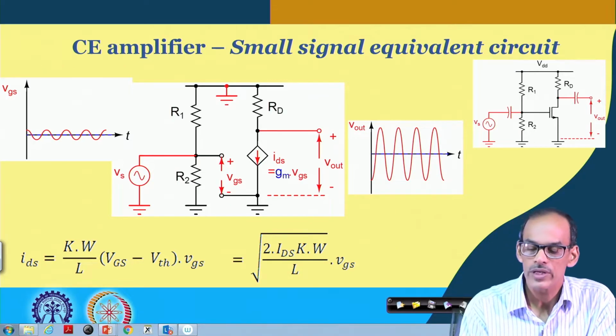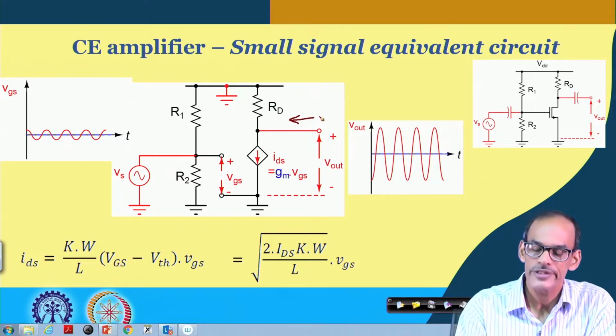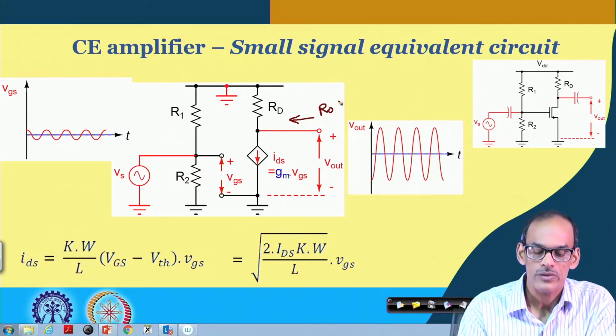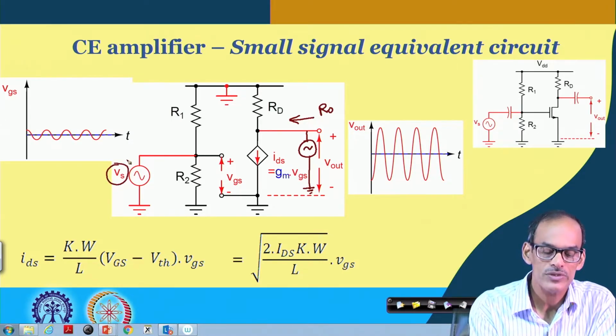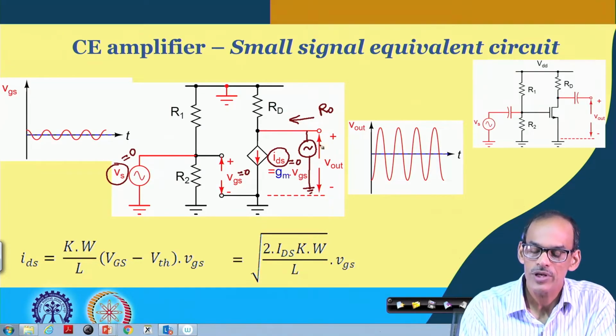So, if you look into this circuit from outside, and see what is the corresponding output resistance. While we will be doing this, as we said, we can connect a signal source here, and then we have to make this part equal to 0. So, once you make this equal to 0, this part it is 0. So, that makes this current also 0. And then if you stimulate this output port by say Vx, and then observe the corresponding current here as Ix,